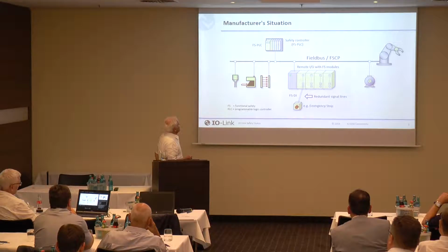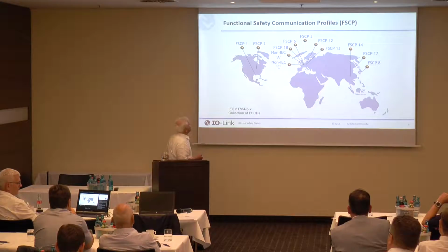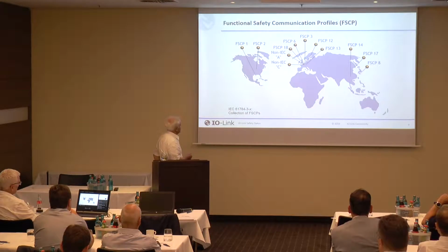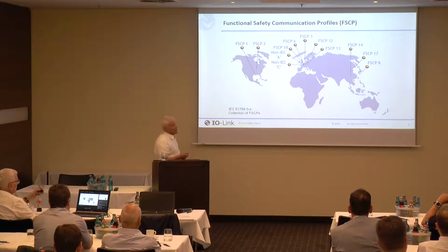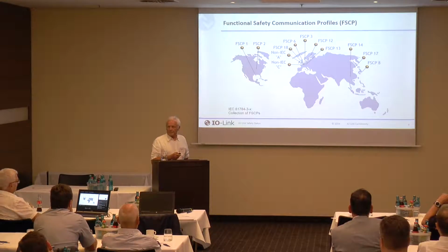So let's have a look at the field bus situation. Yeah, IO-Link safety versus a lot of FSCPs worldwide. They are all standardized in the IEC 61784-3-X. I was working in this area, and we are now trying to establish IO-Link safety within this working group in the IEC.